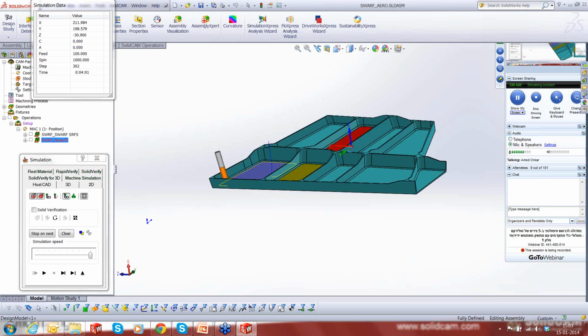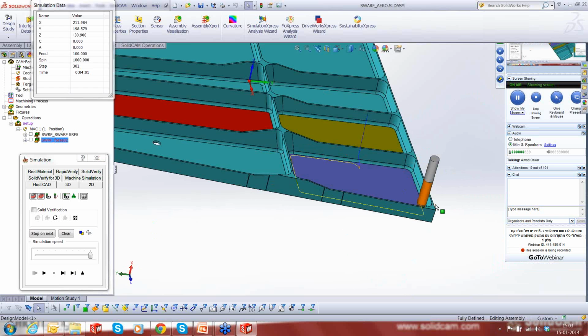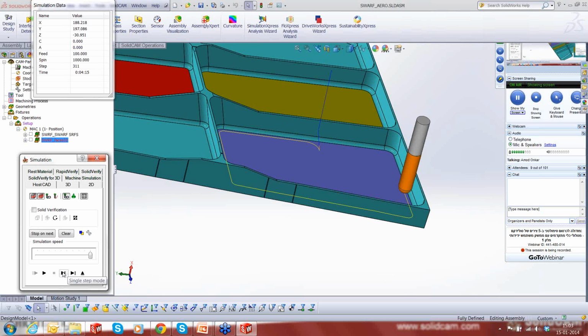Now we no longer have that crazy move in which the tool almost started becoming horizontal. So we have got a very nice tool path now. What this also demonstrated is that in spite of having everything automatic, you still have options to control many things in swarfing, but they're all switched off. You need to switch them on only when you get into issues or need more control of the toolpath. As you can see, right from swarfing onwards in SolidCAM, a lot of things have been automated.